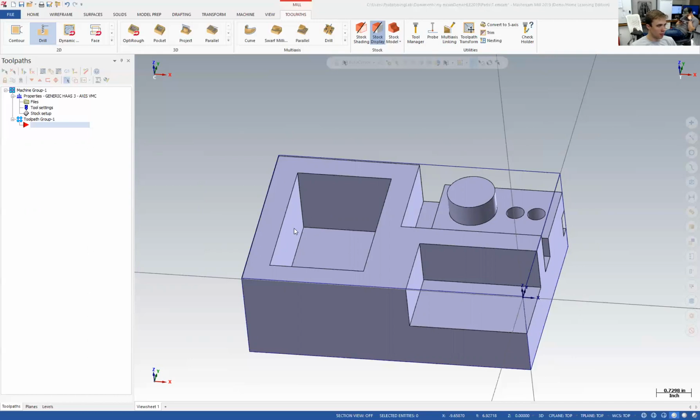As odd as it might seem, you need to understand how to create your entire part before you start camming it. What you don't want to do is start blindly stabbing in the dark and then work into a spot where now it's not possible to make your part. Order of operations is going to be very critical typically. What tools you use is important, and where you put your datums is also very important. So there is the introduction to MasterCAM setup, its basics.